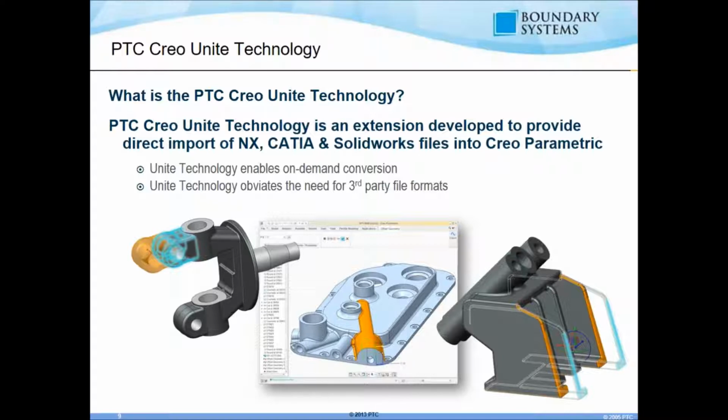Do you want to convert this file now? And literally, it's just a one-click button to say okay, and Creo will convert that file from an NX to a Creo PRT file. And then you can continue making your change to the file, right? So literally, it's just a one-click button to convert the file, and you're on to making your design change, right?